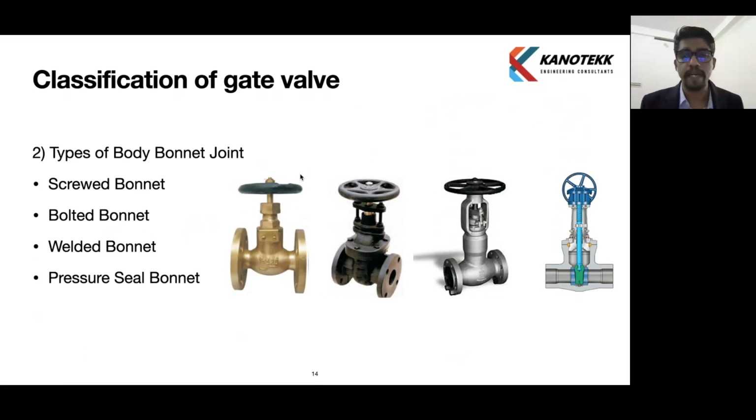And next one is the welded bonnet, which is the third picture. The welded bonnet is widely used for high pressure applications, and where maintenance is not required or a replacement is done. In such cases, a welded bonnet is used.